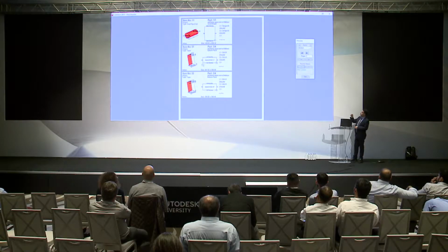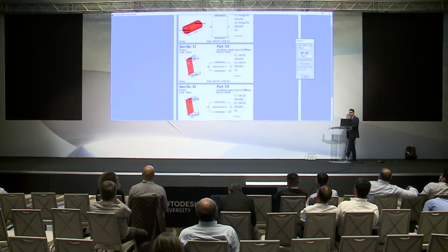Similarly, if I'm looking for a different type of label for each and every piece of my duct which is going to be fabricated, I want the part report. When I look at every piece of equipment, it shows what my length is, what my width is, the weight, and the height, every piece of information which I'm going to send for estimation. Similarly, I'm looking at a different type of report, which will probably be a label again, but in a different way. So I'm going to go for a part label. The part label gives me every part's dimensions, X, and all lengths within the height.